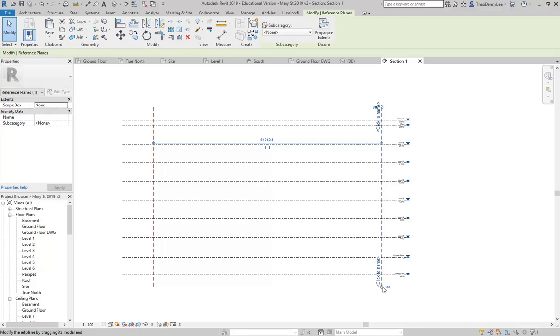Oh, you haven't turned cropping off. So click on the button down the bottom next to show crop region. There's a button that looks like the cropping squares. Click on that so there's a cross on it. There you go, that's it. So you were drawing them, it's just so hidden.